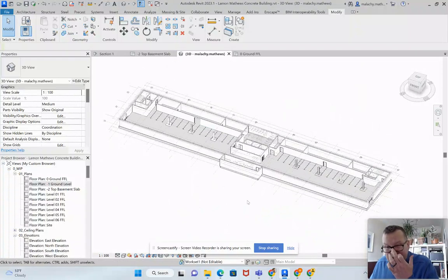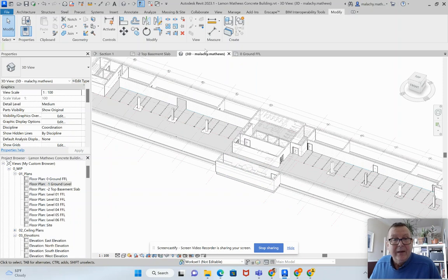I suspect, don't do this now as yet, but I suspect that 300 is not sufficient in terms of the thickness of the walls there. And Pierce had mentioned in studio that the columns are going to be kind of 450, 500 square or rectangular. I'm going to use square columns because I prefer to use square columns, because I know I'm going to have to fix a substructure of cladding rails onto the columns. And it's easier to do that with square columns than it is with round ones in this case. All right, so that's my reasoning behind that.